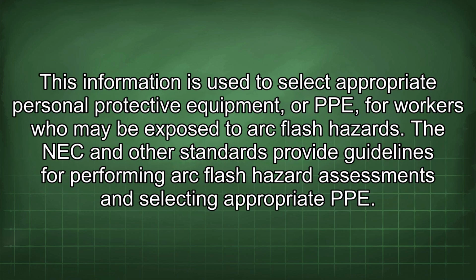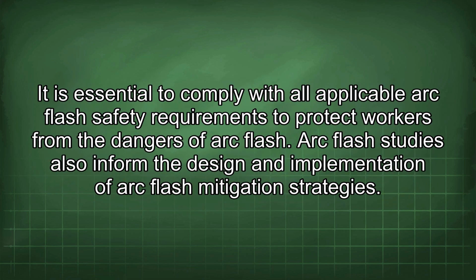Short-circuit calculations are used to determine the arc flash incident energy levels at various locations in the electrical system. This information is used to select appropriate personal protective equipment, or PPE, for workers who may be exposed to arc flash hazards. The NEC and other standards provide guidelines for performing arc flash hazard assessments and selecting appropriate PPE. It is essential to comply with all applicable arc flash safety requirements to protect workers from the dangers of arc flash.